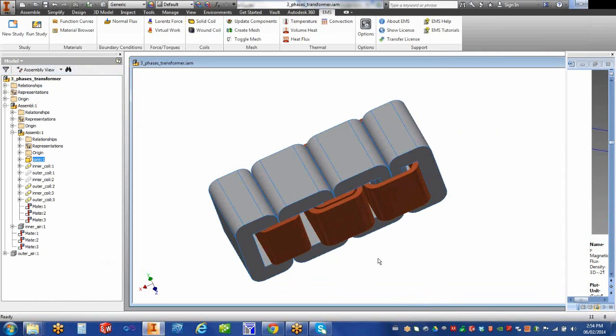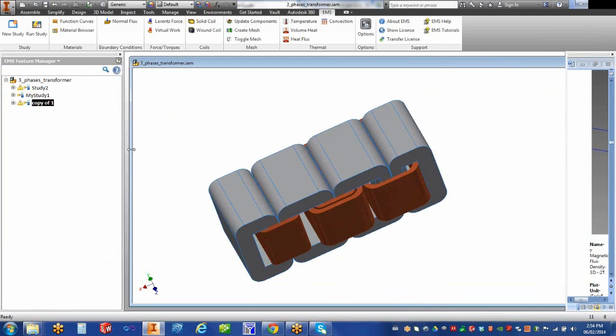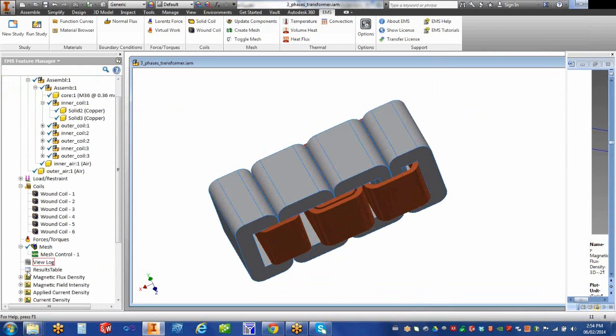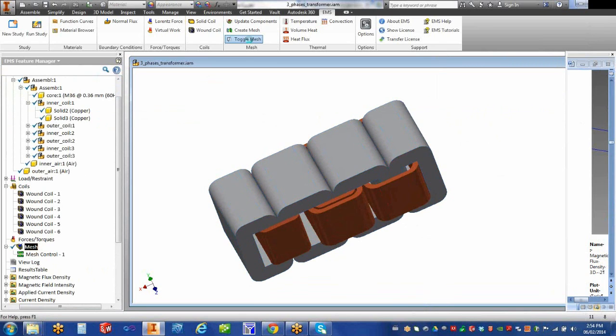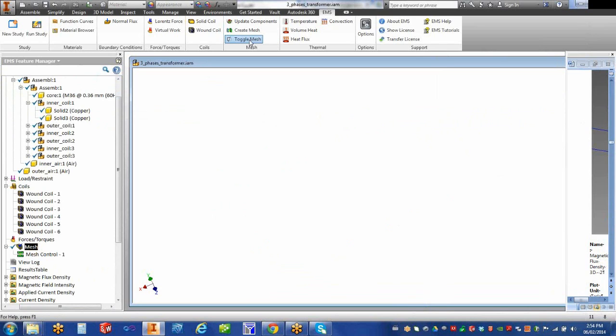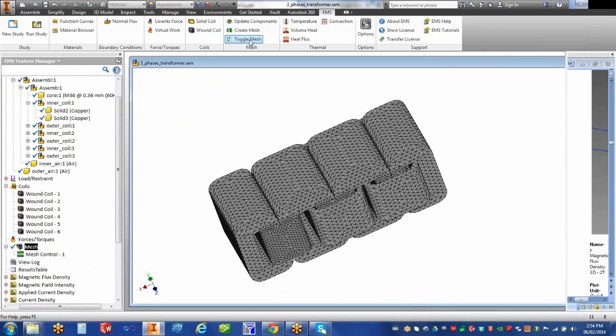Because it's finite element, there's no limit on the complexity of the geometry, because at the end of the day, us as computational people, we see things as a mesh. So as long as we can mesh it, we can solve it, because internally we look at one tetrahedron at a time. So you could have air gaps, you could have a very complicated geometry. It's really your computer memory that is the limit.